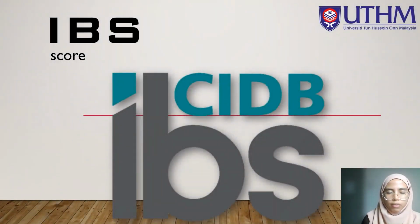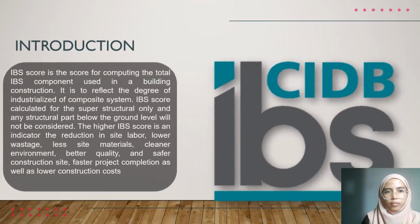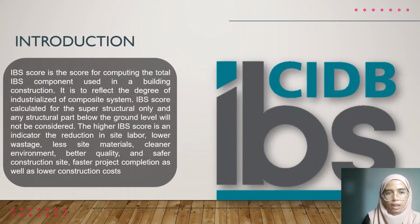I, Nurul Afifah, will now explain the IBS score in this project. For introduction, the IBS score is the score for computing the total IBS components used in the building construction. The IBS score is calculated for the superstructure only, and any structural part below ground level is not considered. The highest IBS score is an indicator of reduction in site labor, lower wastage, less site material, cleaner environment, better quality, and safer construction site, as well as contributing to lower construction costs.